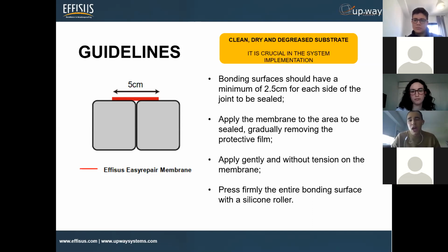If you have a surface that is polycarbonate, or polycarbonate and aluminium, or glass, send the details to João, and you will see if 2.5 centimeters is the minimum. The 2.5 is the minimum, but to be careful, what we usually do is at least 5 for each side. So 10 centimeters is the most common situation, or 15. It depends.